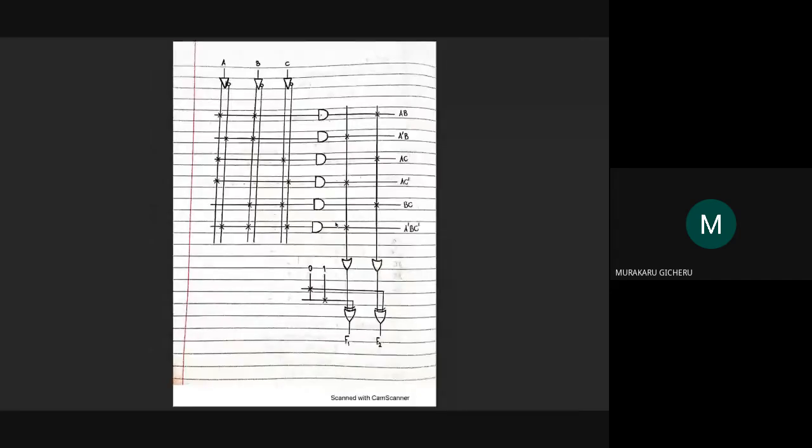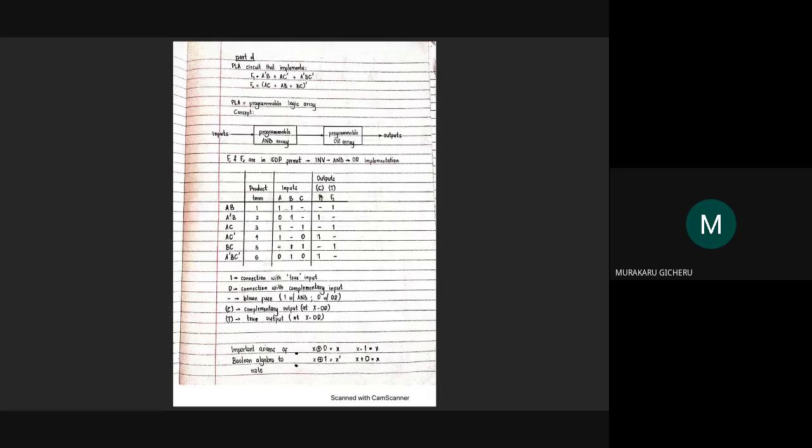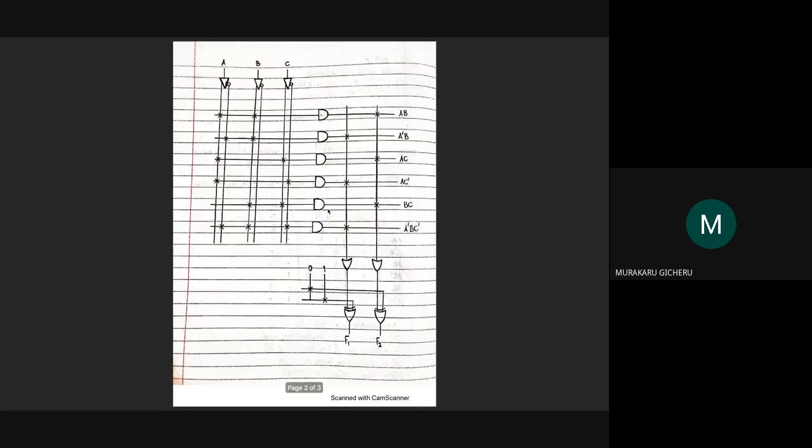That's not important. So now for the PLA, how you will put these crosses is all in this table. If for instance we're going to take AB, we're going to keep the fuse of A intact and the fuse of B intact, and then we will blow all the others. C will be blown, and not A, not B, not C are pretty much irrelevant.